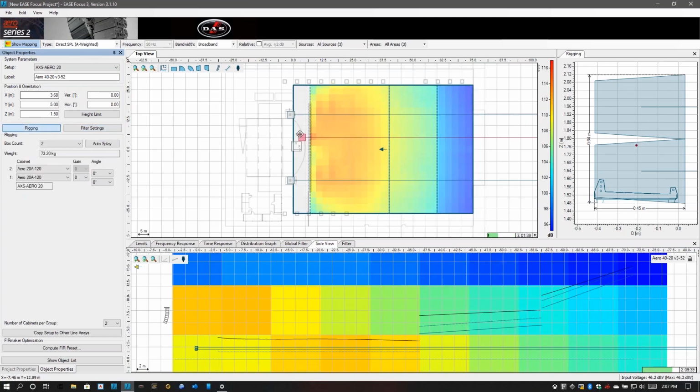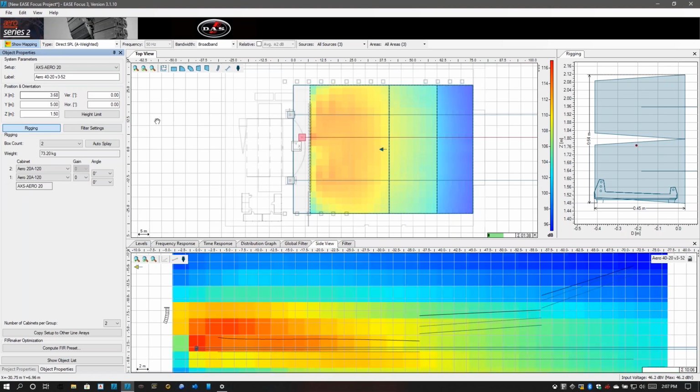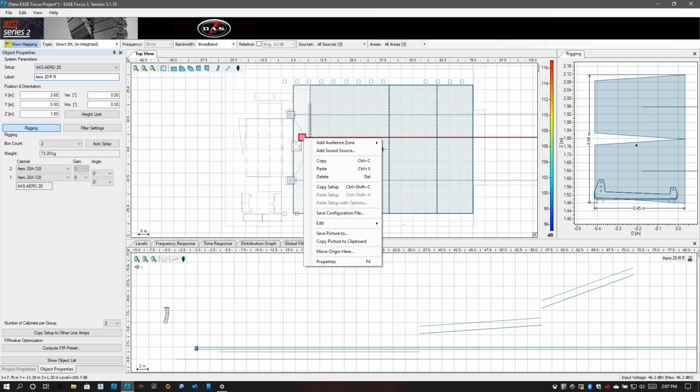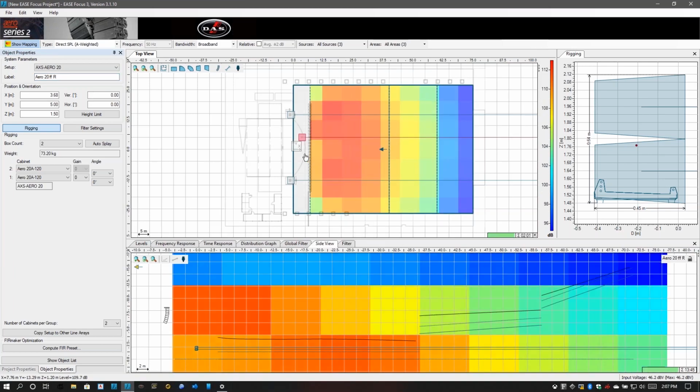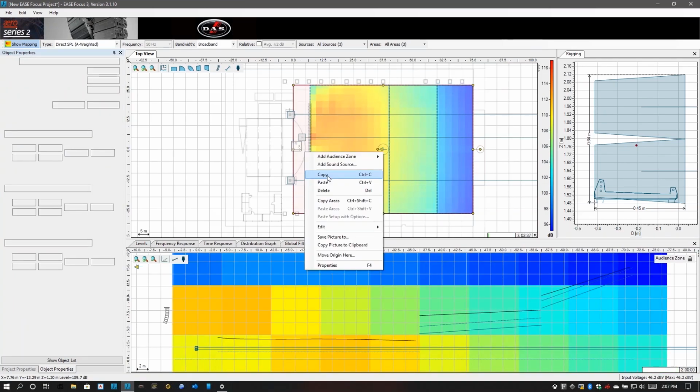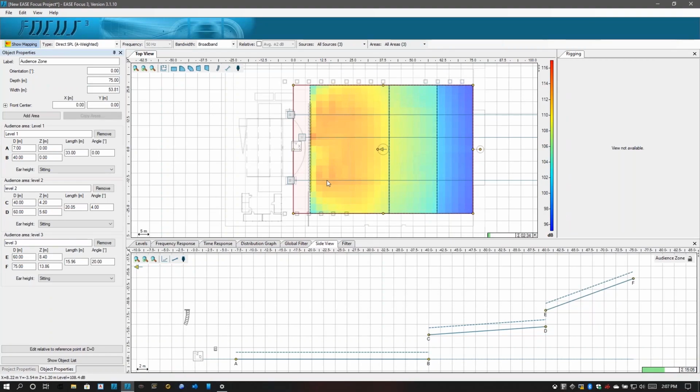And then once you know the placement that you have put it and your cardinal positions and your heights, we can also first name it, 20 front fill left. Let's say we only need one more set of front fills. Once that's done, I can copy, paste it, place it where I need it, and load.